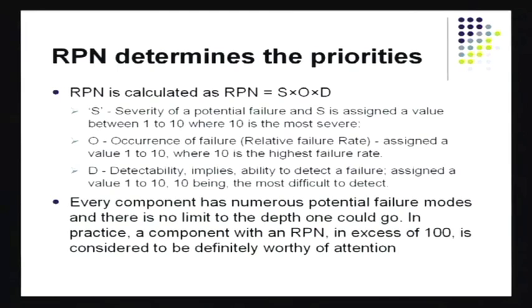And these numbers come out as the result of this FMEA analysis. So I've got here the same formula there. S is the severity, O is the occurrence of failure, which is the probability, and D is the detection capability. These things together, when they are multiplied, you end up with RPN. RPN is the risk priority number. And basically, if you've got RPNs on different actions there, you should really go with the one that's got the highest RPN.